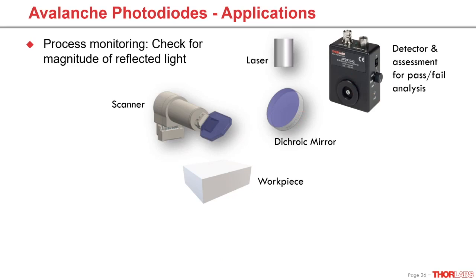Starting our application, the first run shows a perfect signal, which was triggered by the flame that was created. Now let's defocus the workpiece and release the next pulse. We can see that the laser doesn't have the energy to shape the material and the reflected signal is absent.